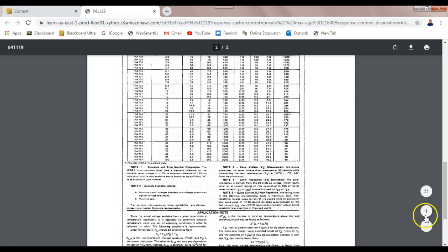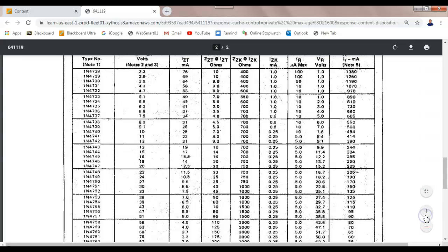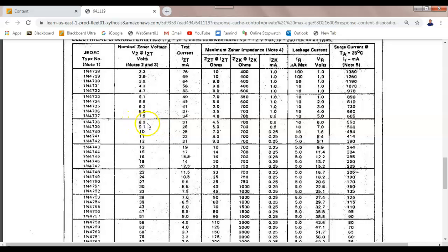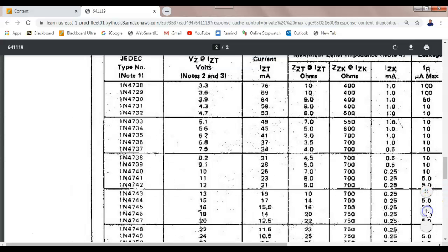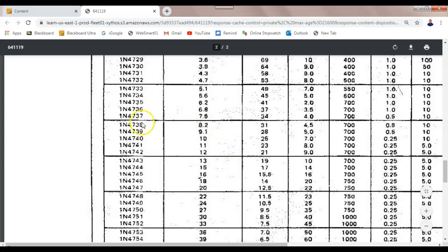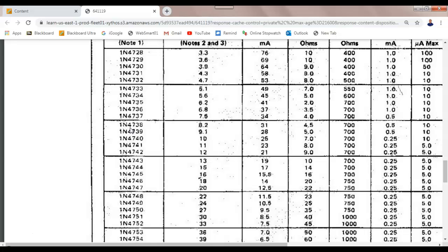And we're looking for an 8.1 volt Zener. So we'll come down the Zeners. It says 8.1? I might have to change it because I don't see 8.1 on here. 8.2, good, thank you. I thought I'd missed that. So the 8.2 volt Zener, we come down to Zener volts, 8.2, so we're going to use the 1N4738. And A, I guess, because it doesn't say that. Does it say plus or minus 5%, or plus or minus 10% on the worksheet?